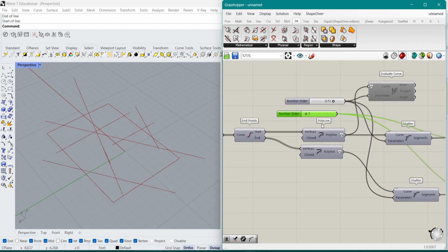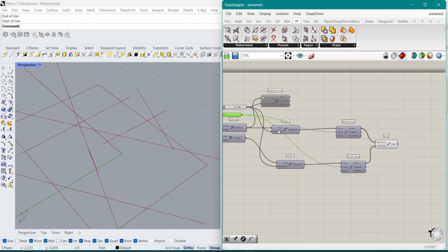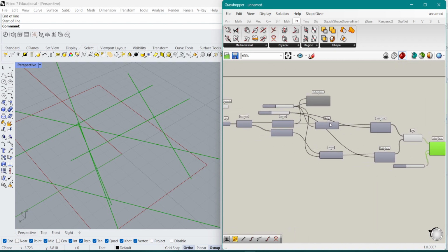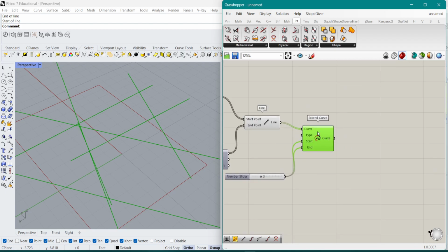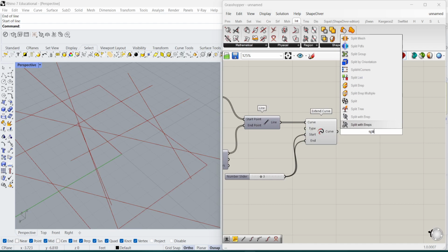Obviously, I might want to make those lines bigger or the rectangle smaller, if I want, for example, to get this line more through, or I can extend them a little bit if I choose to. Perfect. Now that we have that, we want to take care of the basic surface. So we're going to use those lines here and then use the split surface command.